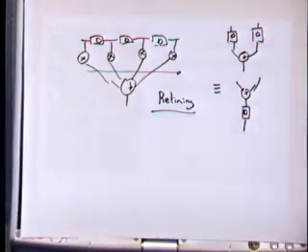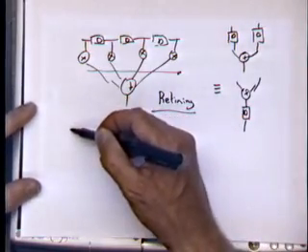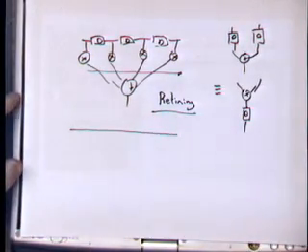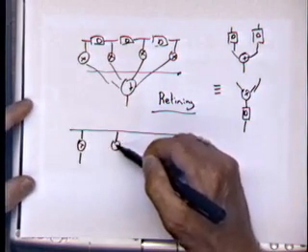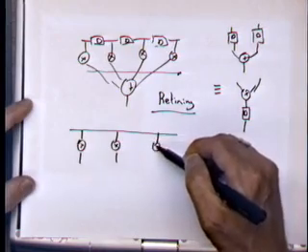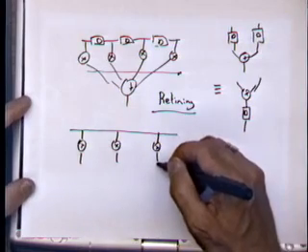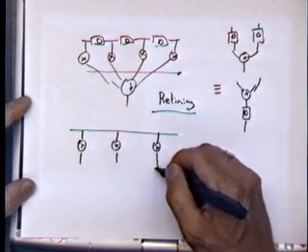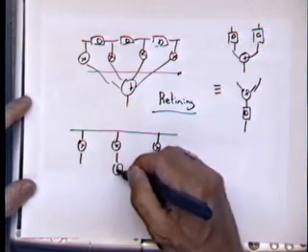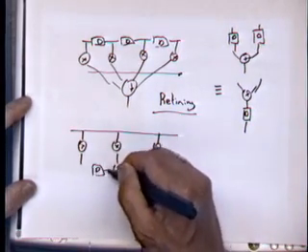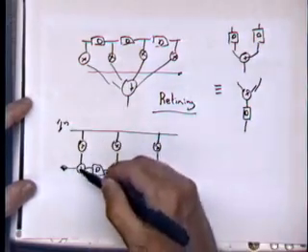So it actually turns out that if you do this on an FIR filter, what I could do is restructure the whole operation to get something like this, where you just take the input and provide all the multiplies on the input, and then you have the structure running in the opposite direction. You take a delay, you put an add here, you put a delay, and you put an add here, and this is the output. This is the input, and this is the output.